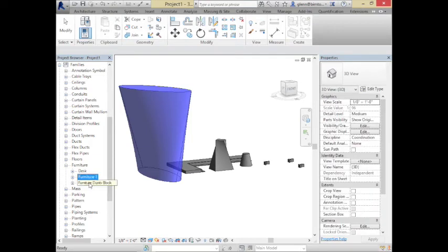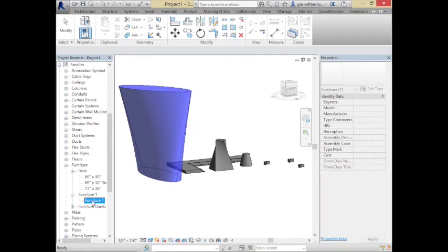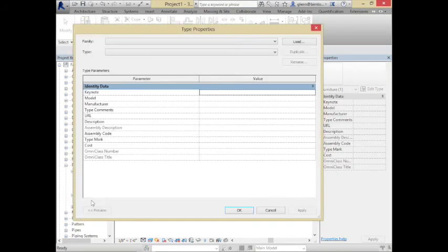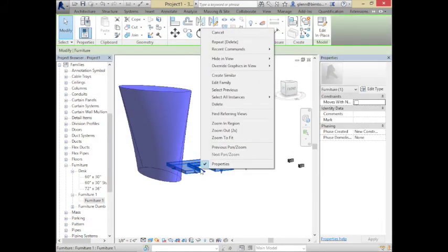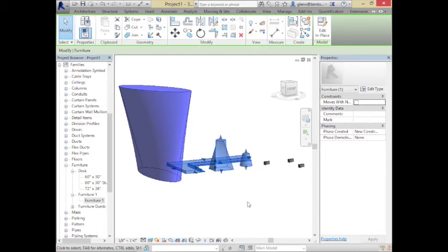Here's his thing, the furniture one, there's my furniture, that's it. Where is that saved to the computer? I think we can't really get it out again the way we want to. Here it is, there is the furniture one. We have it there, but it's actually just stored in the project itself. So basically, we can't copy families from project to project. Oh, you can't copy an in-place family. In-place family, and that's the real limitation between doing that.